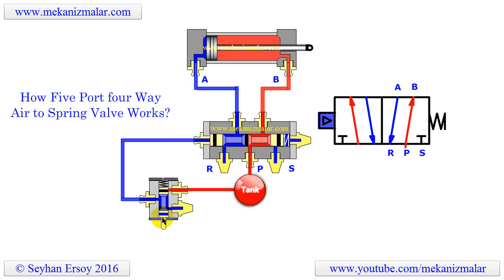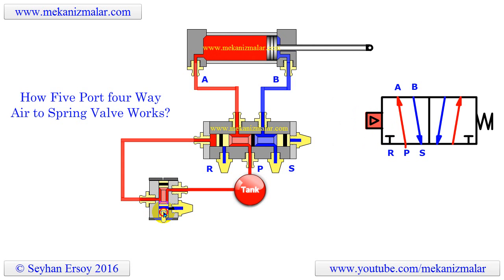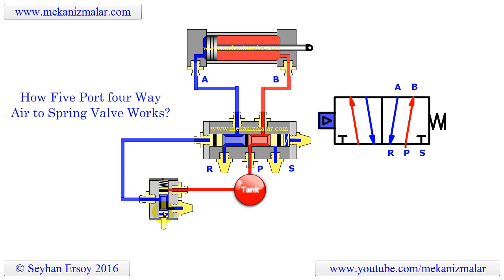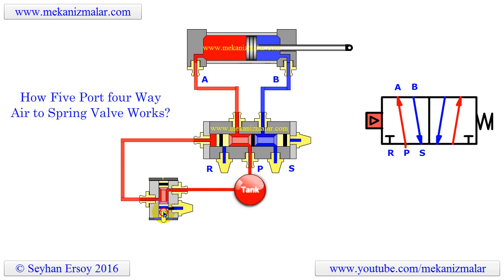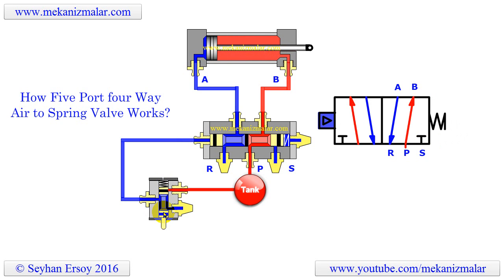By pushing the button on the valve, it returns to its previous condition by spring when the force is removed from the button. The force condition on this valve is emulated in this animation by the mouse clicking on the valve. The mouse release action emulates the force removed from the valve button. This will cause the valve to return to its normally closed position by the spring action.